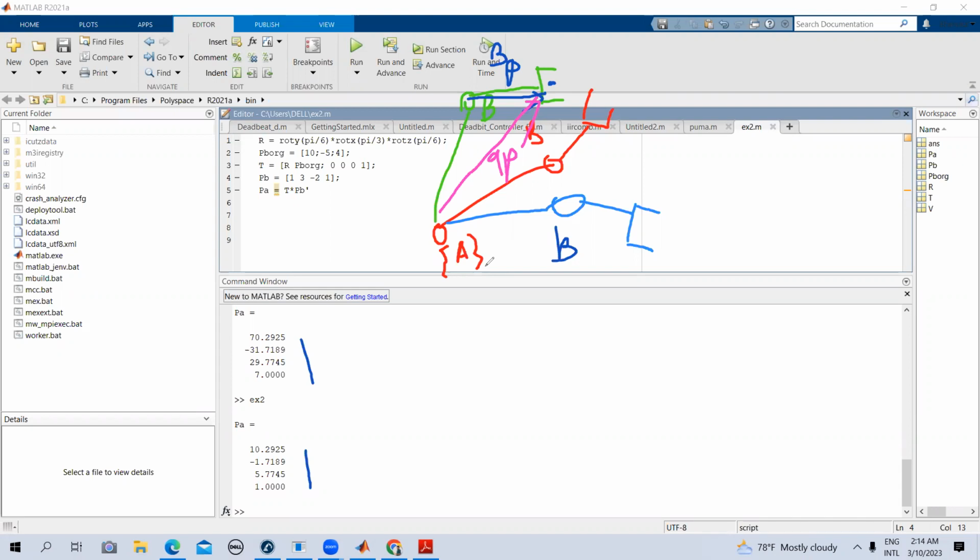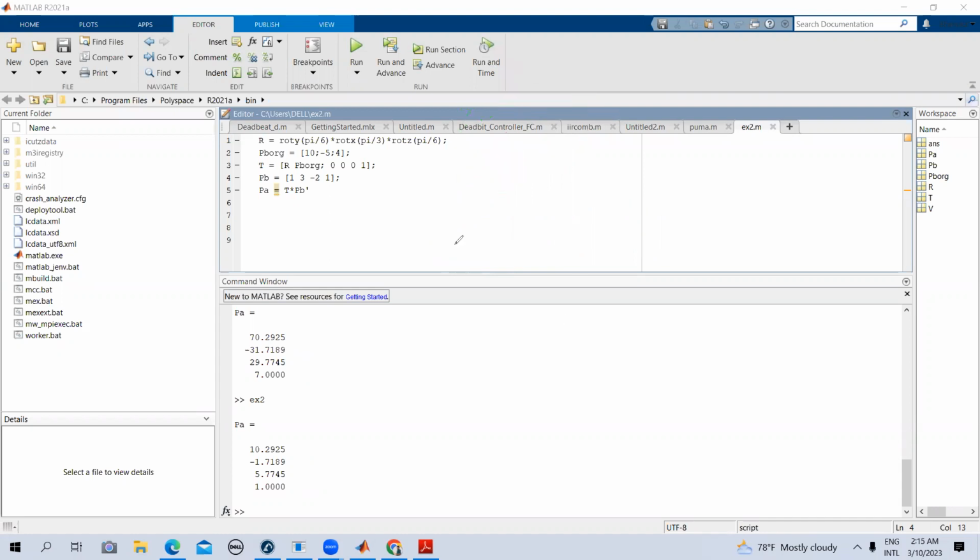Now, if you all understand what this is, then that's basically it. You can simply find any point in 3D space if you know these particular parameters, which are the position vector with respect to the origin and the rotation matrix. Then you can compute the transformation matrix, and then you can find any point in 3D vector space as long as you know this. So I think that is clear. You can vary these and play around with the program. You can try out new things.